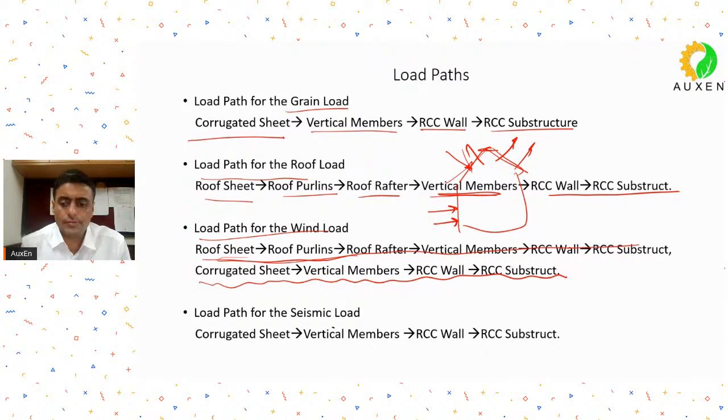And for seismic, because most of the load will be due to the grain, that will act on the corrugated sheet first, then to this, then to this, then to this. So you have simple load paths for your seismic loads.